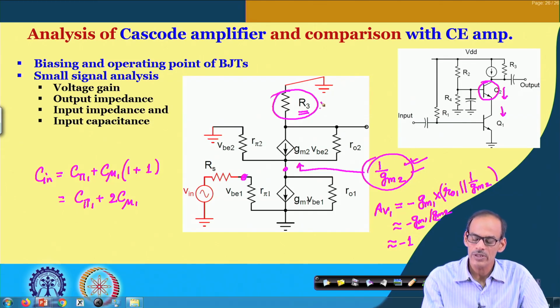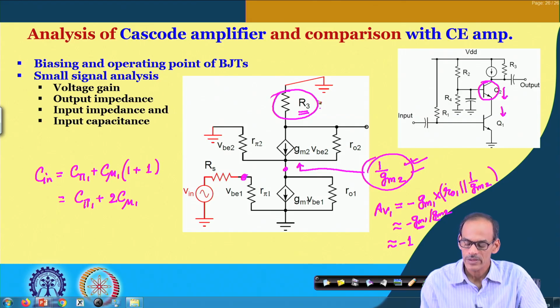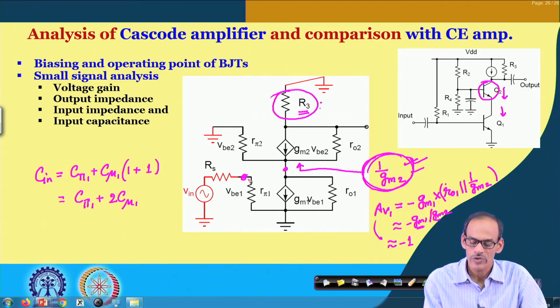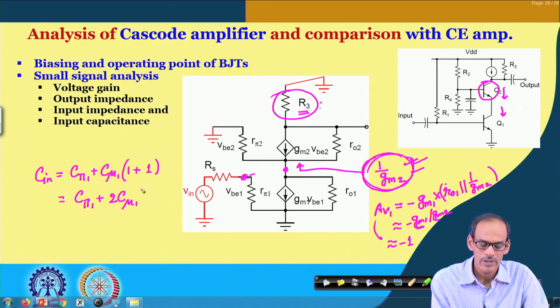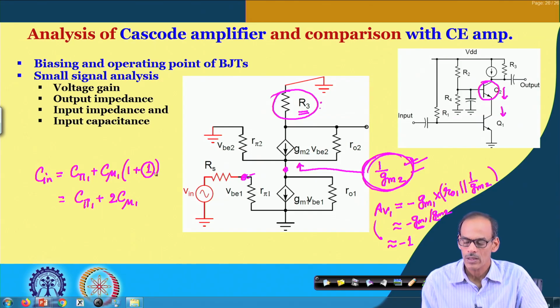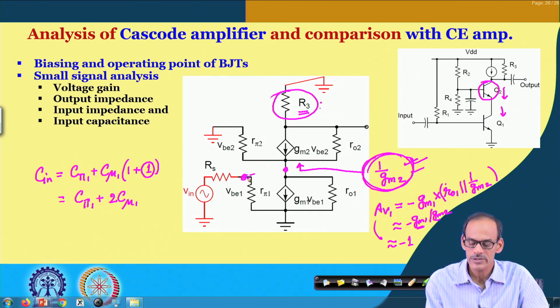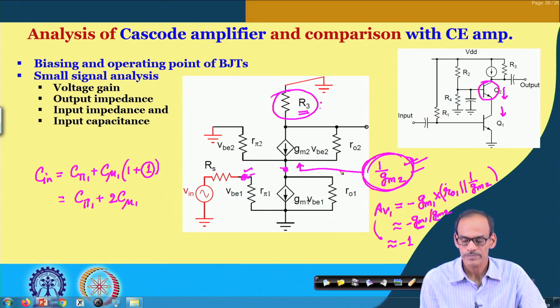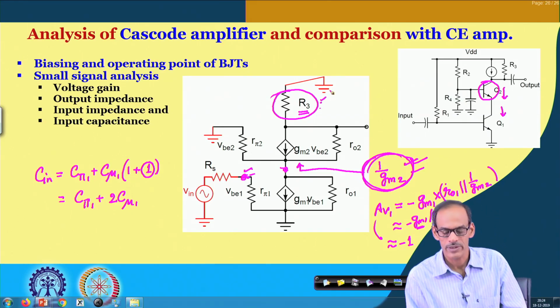If this R 3, on the other hand, is very high, that may increase this resistance, and the consequence, of course, is that the voltage gain here will increase. So, if the gain from here to here is increasing, then this factor, instead of 1, will also increase. But typically, it is quite fair to approximate that the gain from this point to this point will be around 1 or 2, depending on the corresponding practical load here.